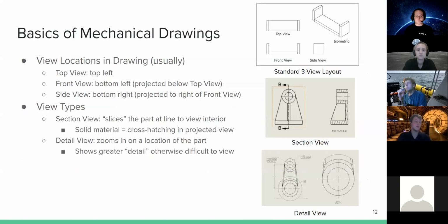All right, an important thing for today is we want to go through mechanical drawings and turn those into solid models. Something to get used to is the way you would actually read this drawing. In this case, we're going to be using what's called third angle projection, which I think the easiest way to think about is if I had an object that you're looking at.